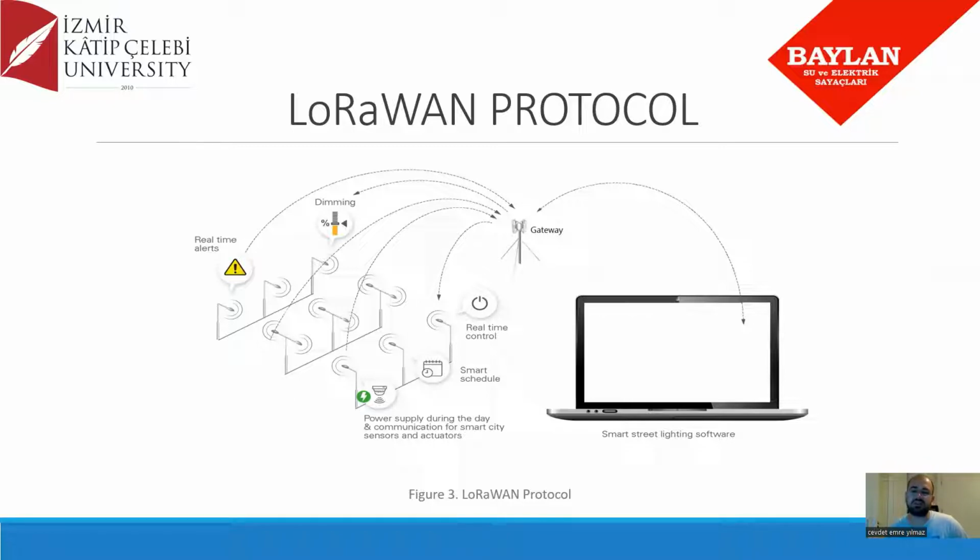Unlicensed frequency channels are used in the ISM band. The radio frequency output power is designed not to exceed the value that can be used without the need for a license. In this way, the cost of the system has been dramatically reduced. This system is used in the ISM band at 868 MHz. The LoRaWAN default class is defined as class C. LoRaWAN adaptive data rate is open. The LoRaWAN activation type is activation by personalization.